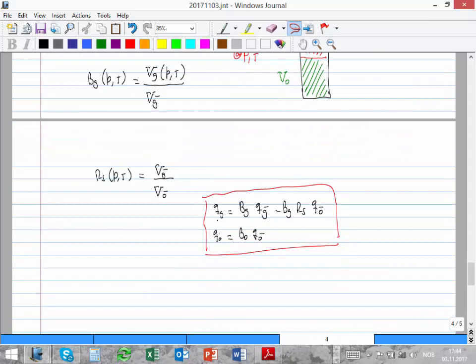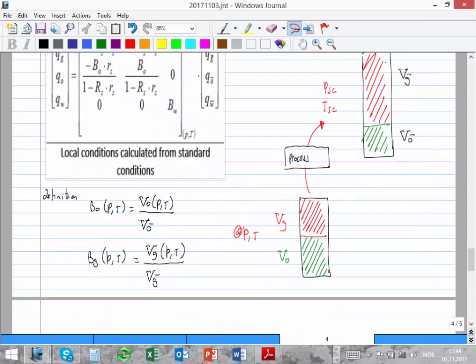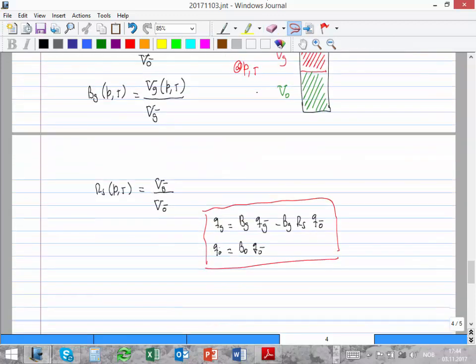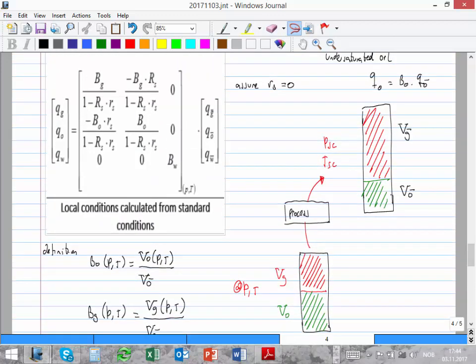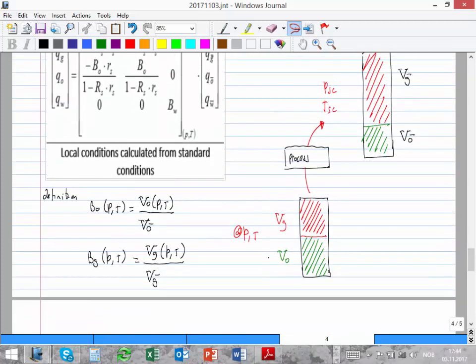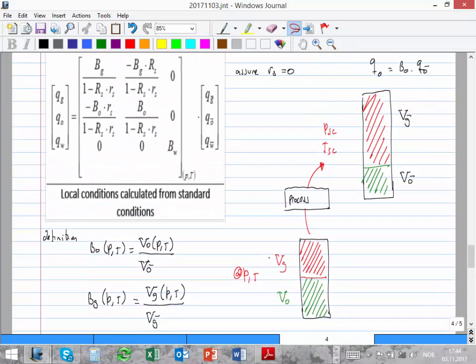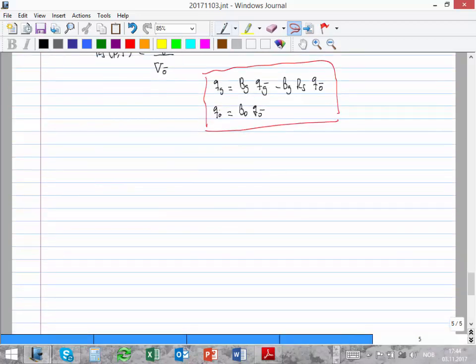I'm saying, well, in the local conditions, first I have to compress all of this gas, bring it to P and T, and then I have to say, well, maybe part of this gas was back in the oil, so I have to take it away from this gas. And oil, I don't have that problem. Oil is just BO, because by definition it's the ratio between here divided by this term. Now to address your question, there is something, if RS is important,